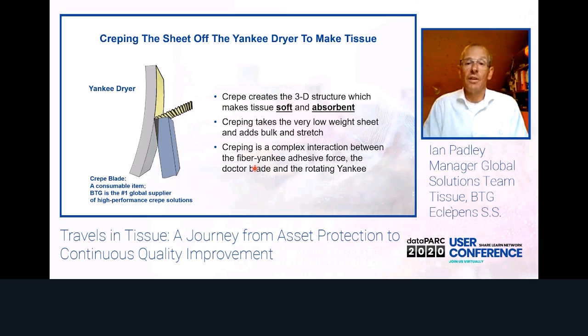The 3D structure is created by the crepe blade. It takes a very low weight sheet and adds bulk and stretch. It's a complex interaction between the fiber and Yankee adhesive forces, the doctor blade which doesn't move, and a rotating Yankee which does move. I have a short animation following here which will show just how this works.